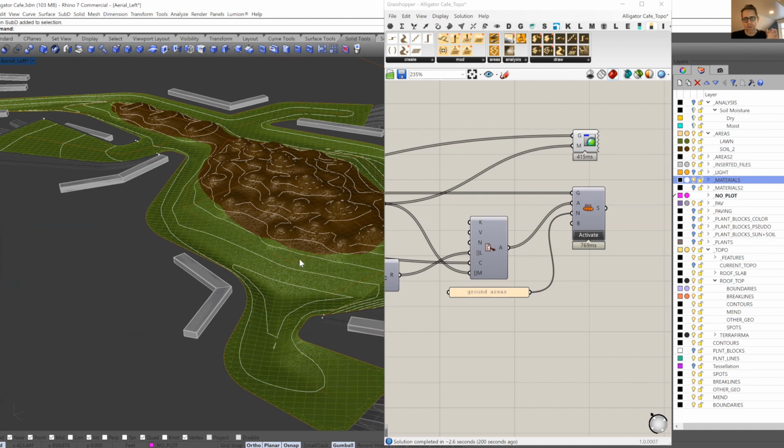The one thing you want to watch out for is that you don't want to try to cut contours through SubD. It's really, really slow. So usually what we do is we convert the SubD back to a mesh if we want to get those smooth contours, and it's super fast cutting through a mesh. You just have to do the conversion back. So anyways, that's a fun thing.